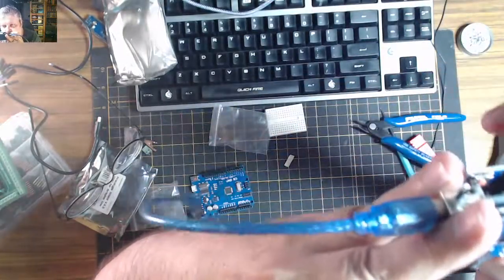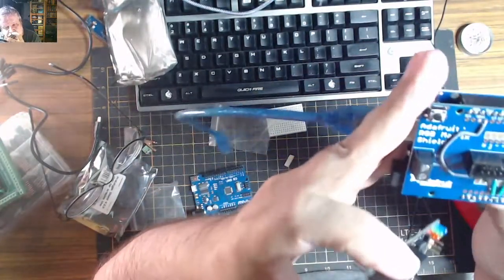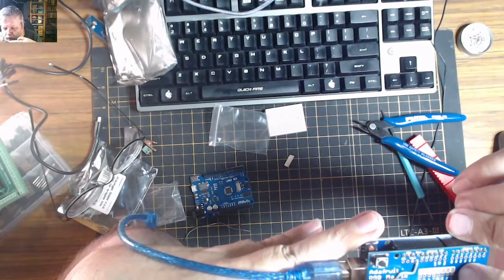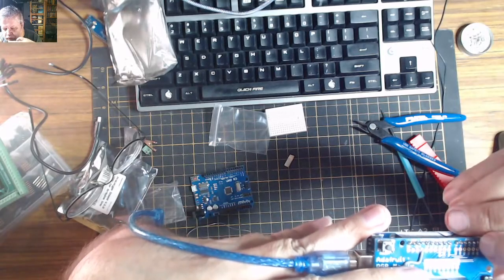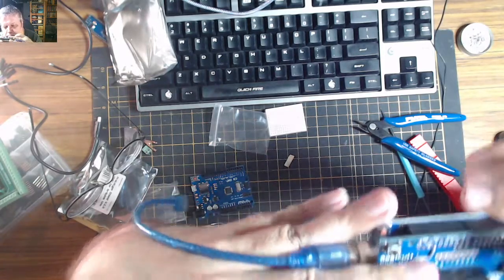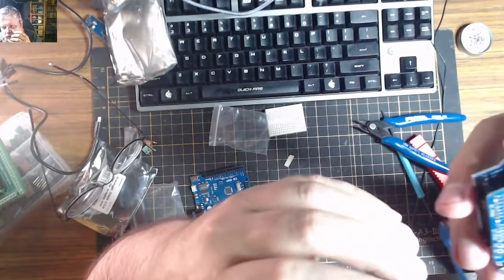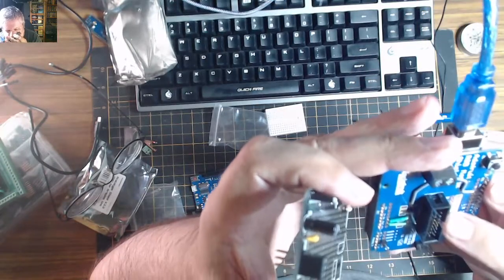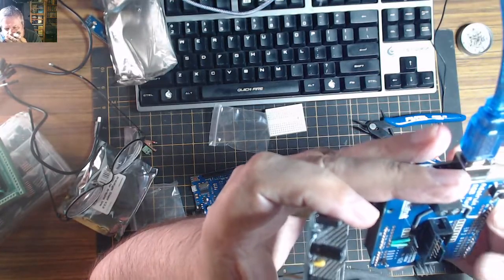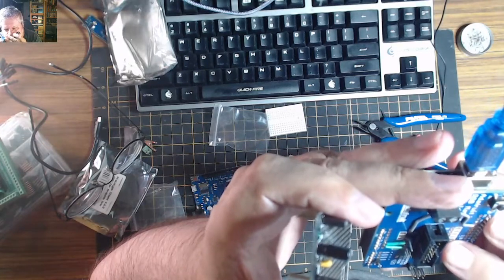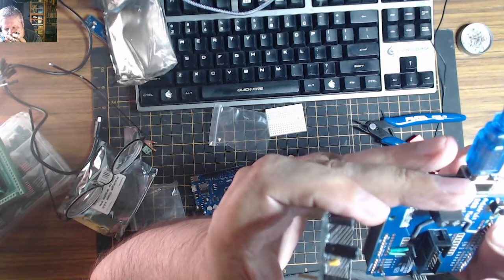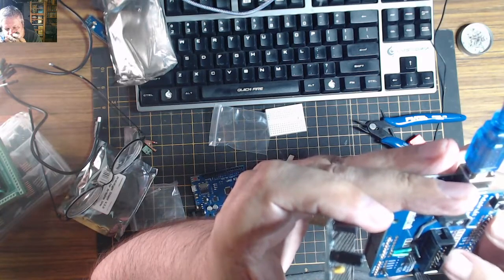The advantage of this one here, of course, versus this one is, see, R1 already goes over here to the right pin. R2, R3. The R1, B1, R2, B2 actually controls the LEDs. A, B, C, D is the data lines, clock, and then you have G1, G2, which is part of the R1, B1, R2, B2.